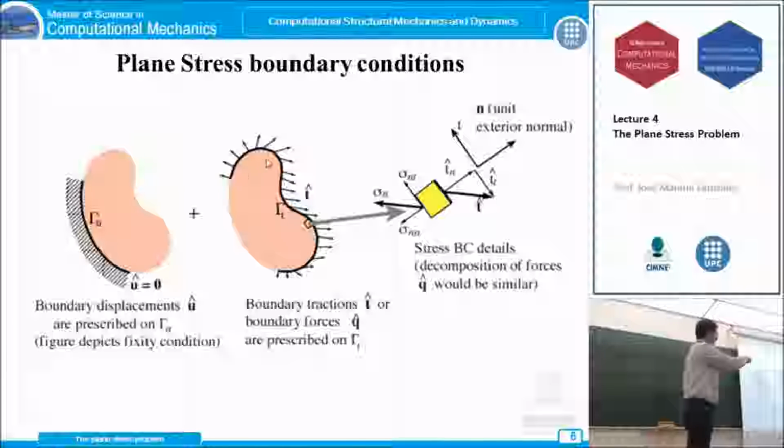And we have a boundary condition which we call tau sub t, where tractions, boundary forces are applied. So we can have all these boundary conditions, displacement and tractions. This decomposition of the boundary domain makes sense in the finite element formulation of the forces. So we divide these two domains to take them into account in the formulation of the finite element equilibrium forces.